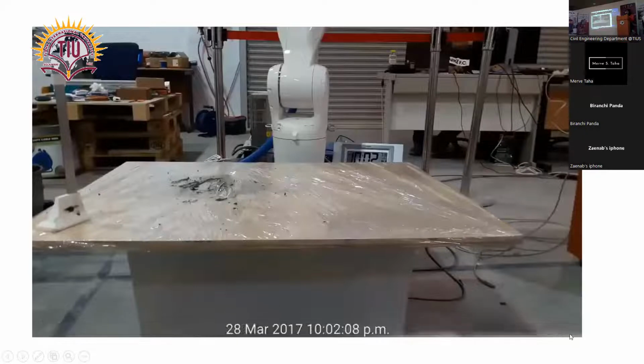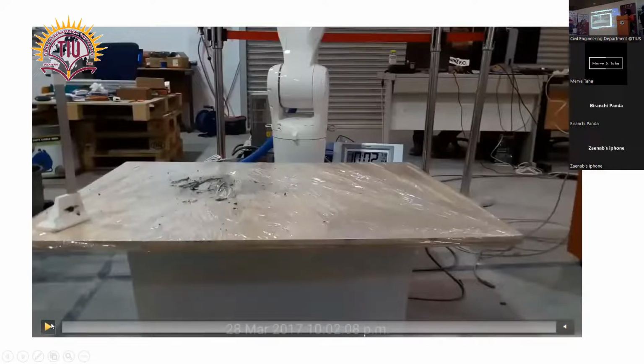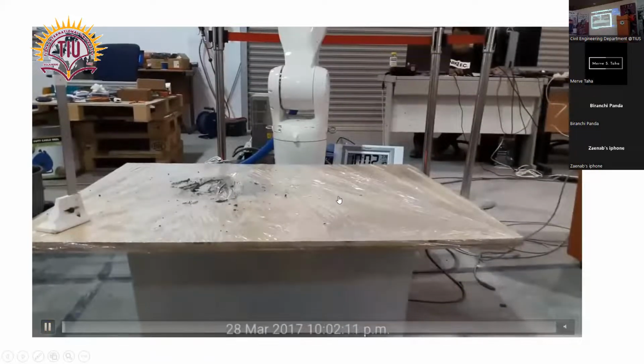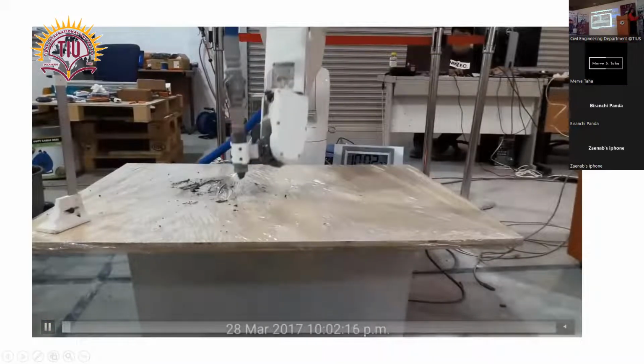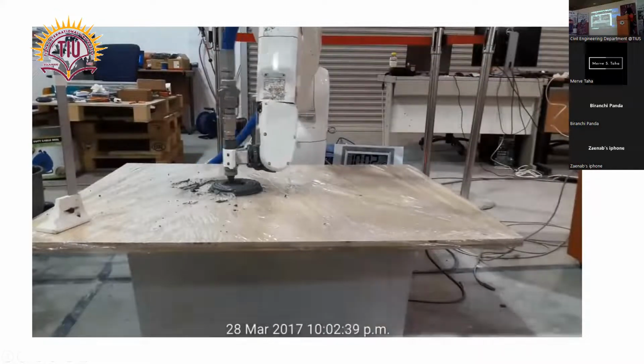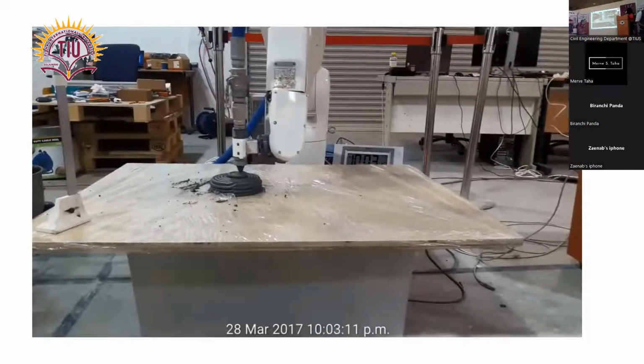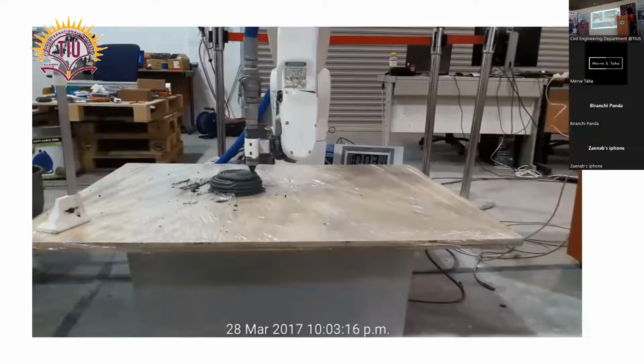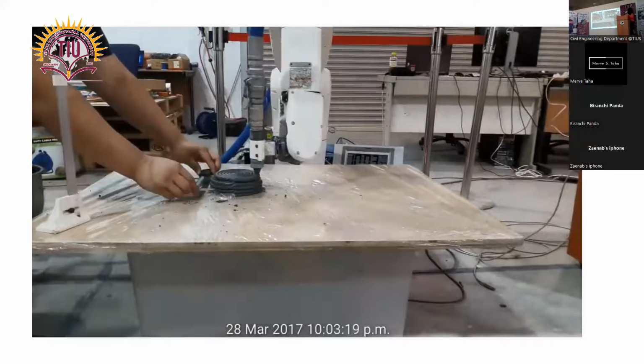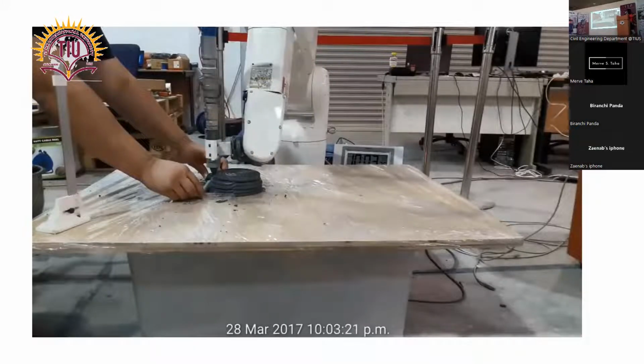In that regard, you can see from this video, let me play it. You can see in this video we are trying to print a geopolymer. And then the printing process can be considered more robust. You can see that we are printing this layer by layer using a small robotic arm. The robot pipe with a pump.